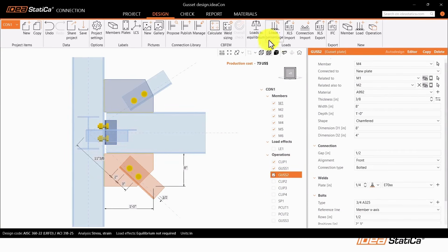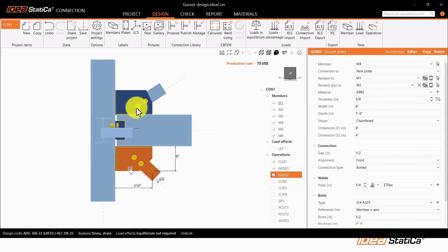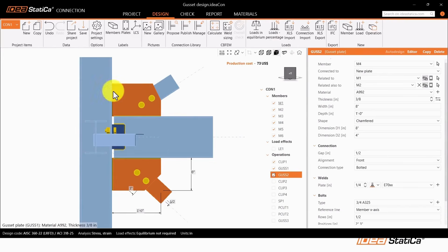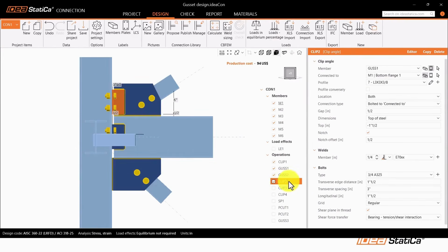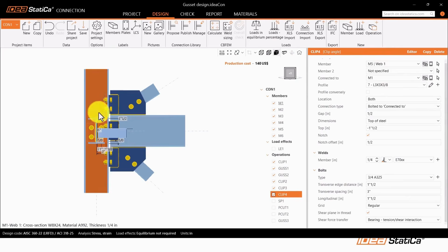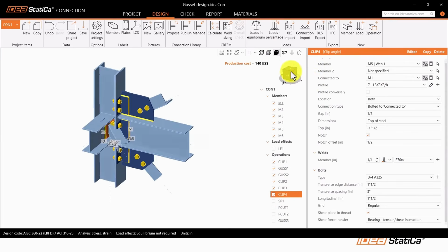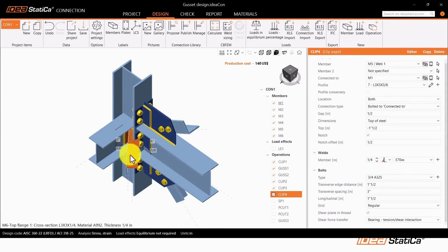Then after that, instead of having just welded gusset plates to the members, Corbin decided to add clip angles from the gusset plate to the column. So you can add clip operations to gusset plates, like in this case. I'm going to activate clip 3 so you can see the third clip operation in this model. Finally, clip 4 is assigned for the beam coming into the web of the column, right? And now we're missing the horizontal gusset plate for this member.